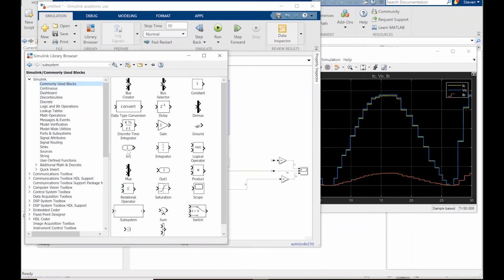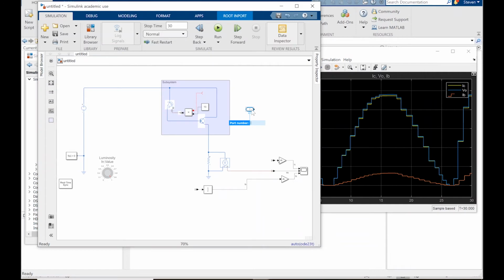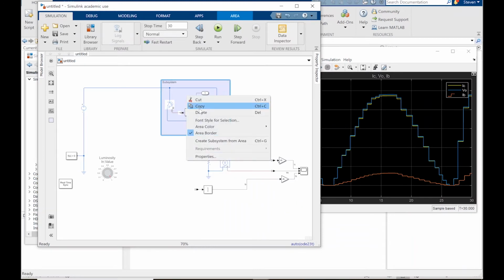Right now, I have to back up here. What I'm doing is adding a Simulink model. This is going to be an input. To talk between subsystems, you have to have connectors. MATLAB is smart enough to recognize the wires going out of the subsystem and automatically put in the proper Simscape connectors. But I need to change that one constant to a Simulink input.